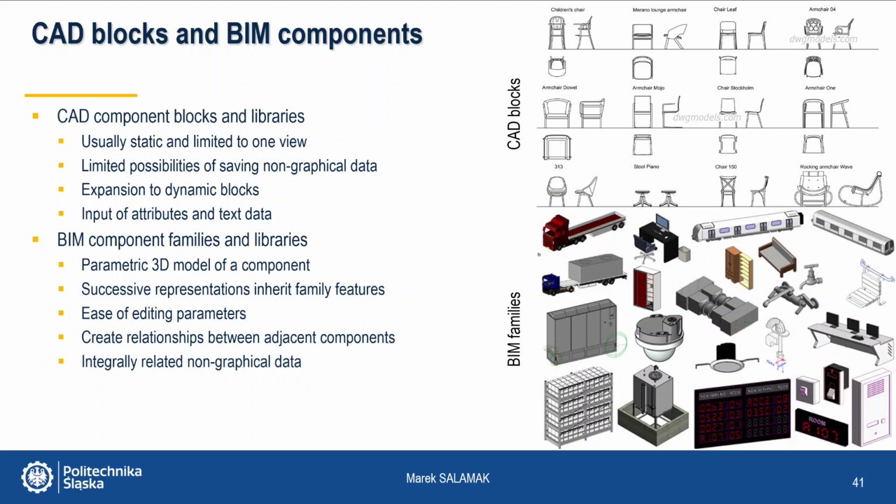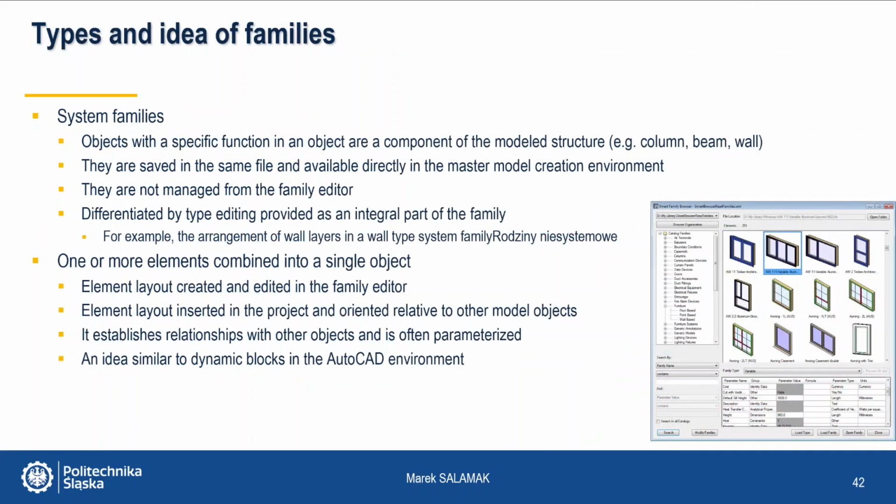BIM methodology changed everything. Together with it, the concept of a family was introduced. Therefore, we distinguish systemic and non-systemic families. Systemic families are objects with a specific function in the model, and they are a component element of the modeled structure.